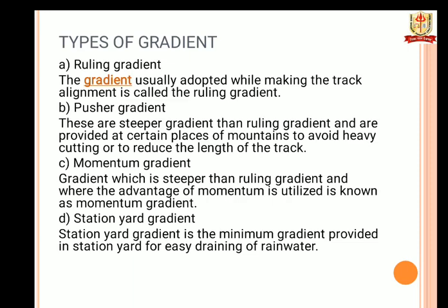Momentum gradient. A gradient which is steeper than the ruling gradient and where the advantage of momentum is utilized is known as a momentum gradient. Station yard gradient. Station yard gradient is the minimum gradient provided in a station yard for easy draining of rainwater.